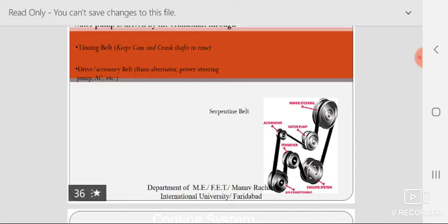You can see all these systems being shown here. These are very complex accessories. This diagram defines the total accessories of the system. You can see the accessory belts, these belts; you must have read about the belt and pulley arrangement. There is a lot of transmission power loss between every two pulleys. And taking this system all together, a lot of power is lost in the system, and the rest of the power is transferred to the wheel. So the wheel ultimately gets less power.